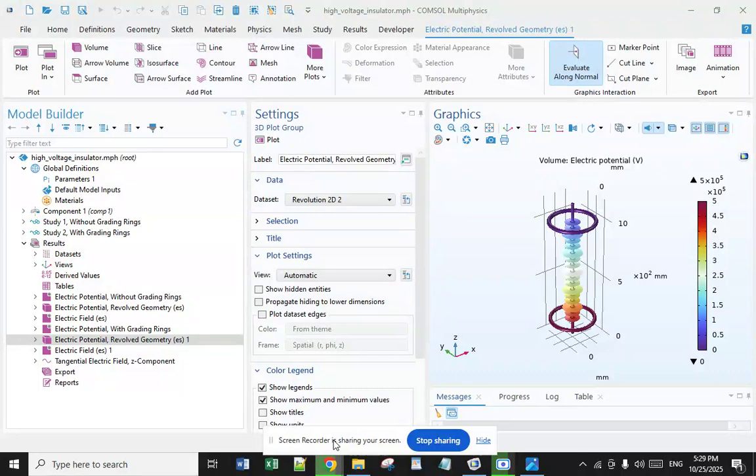This is crucial to prevent short circuits and other types of electrical faults that could compromise the safety and efficiency of the electrical system. And the maintenance and design considerations. Maintenance of support insulators involves regular inspections for cracks, surface contamination, and material wear. Periodic cleaning and electrical testing are also essential to ensure their optimal performance and prolong their service life.